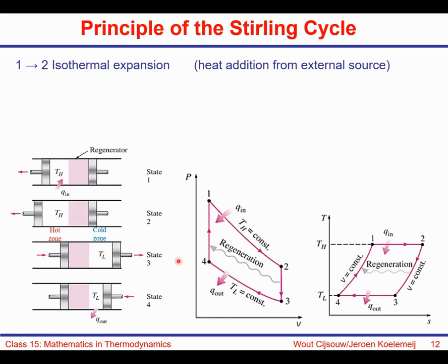So here is a depiction of a Stirling engine that is a cylinder containing two pistons. The pistons can move. They're connected to the same flywheel or crankshaft, if you will, but they don't always move in the same direction or at the same speed, as we will see. This Stirling engine has a body of gas that is going to be shuffled between a hot zone and a cold zone. So everywhere in this graph here is the hot zone, and this is a cold zone.